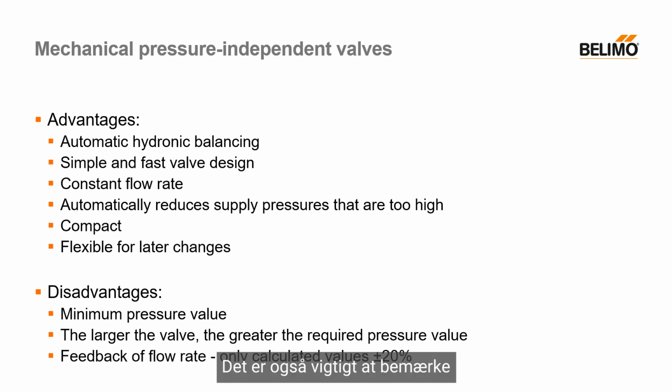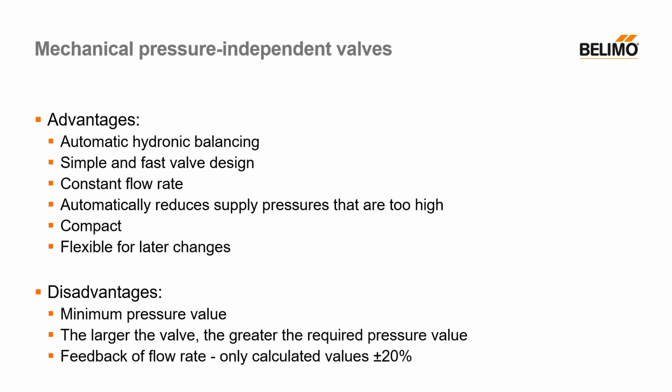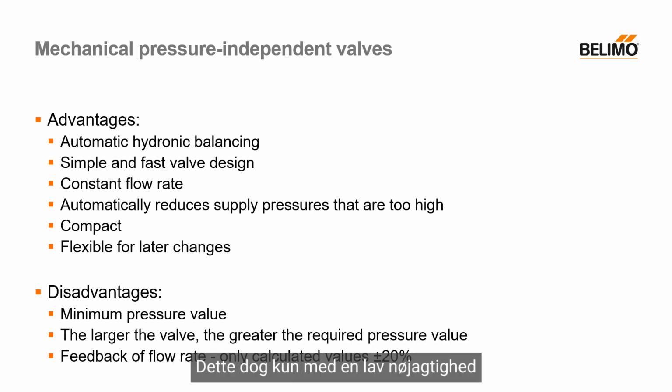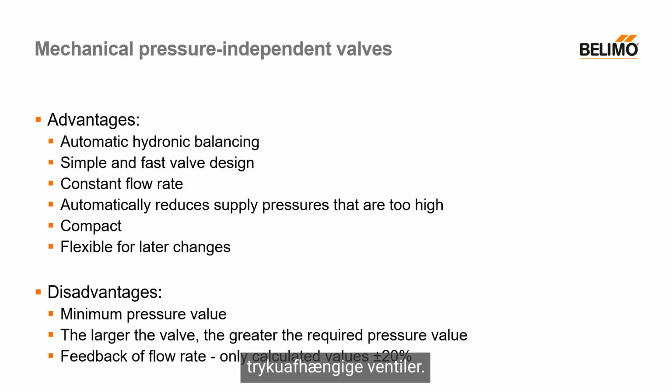It is also important to note that flow rate feedback is only possible with calculated values. This, however, only with a low accuracy of at least plus or minus 20%. In most cases, however, the difference is significantly greater. Let's now take a closer look at electronic pressure-independent valves.